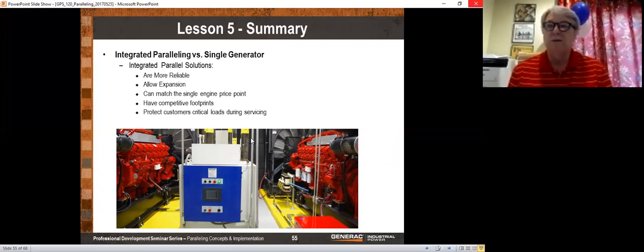So what we actually do is fire up our standby generator and use it to test that motor, so the motor is being tested on standby generator power rather than utility power. If you have a generator and you can switch some loads to it during a peak time, that's really easy and simple.